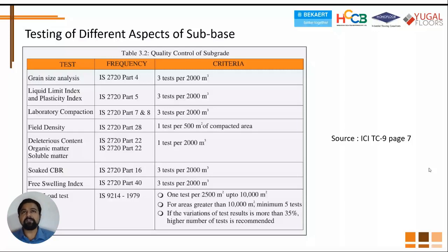Say for example, we specify 98% proctor density for each layer before proceeding to the next layer. So instead of finding out after we finish everything that our k-value is not according to our initial assumptions in design, what if we are able to establish on the day that we are filling itself that we get a 98% proctor density and we move on to the next level? So we're more likely to have the desired end result than when we are testing just at the end. So this is just to give you an example of how we can use a process control in comparison to a product control, right?